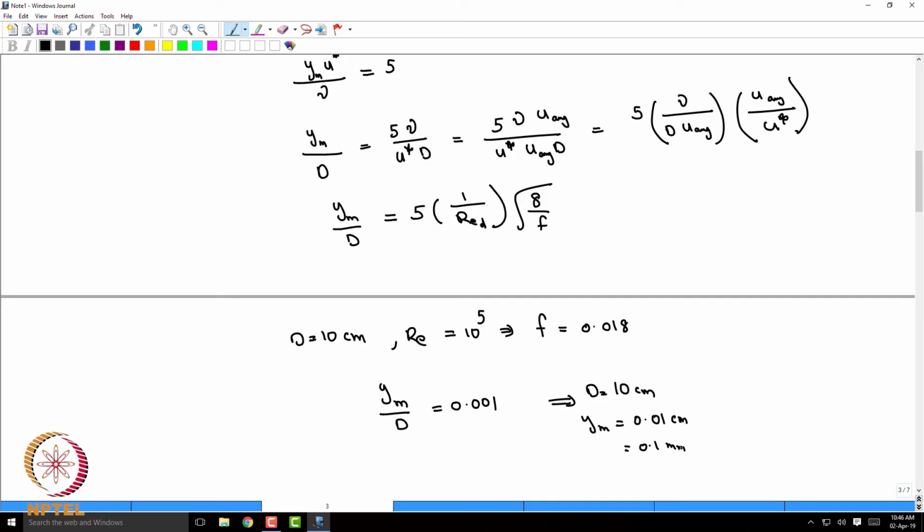So for the laminar flow, it's basically going all the way there, right? There is nothing like a wall layer that is confined to the wall. There may be a small region where the roughness could affect it, but basically the viscous action will immediately smoothen it out because it's spanning all the way up to the radius. So that's why it does not get affected.